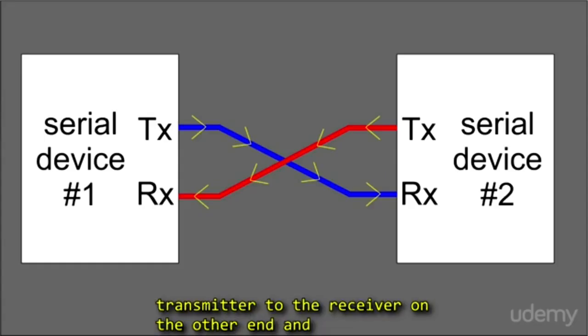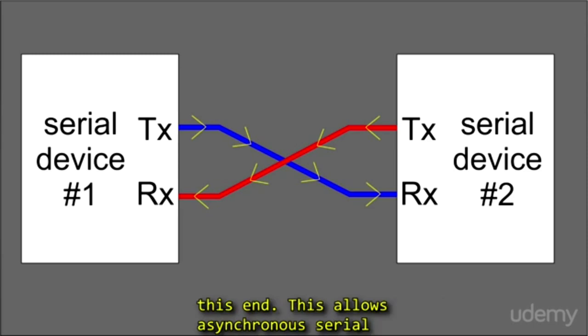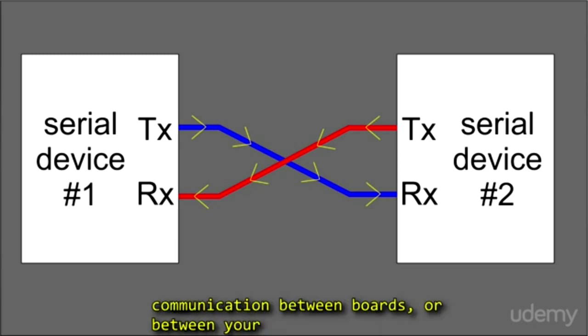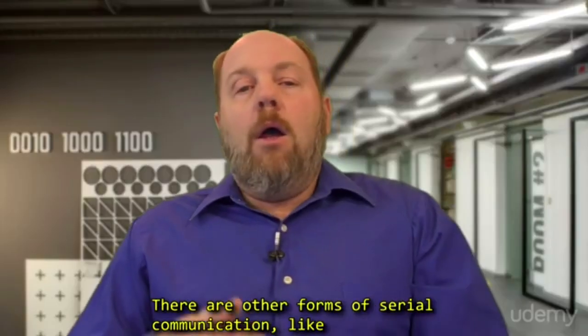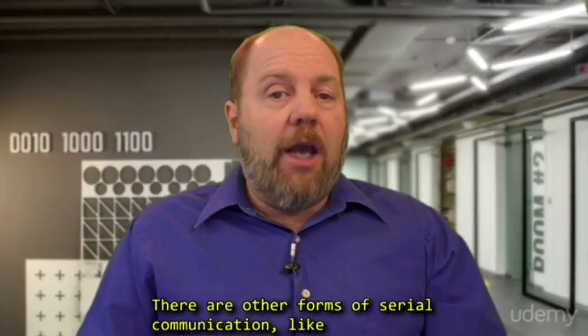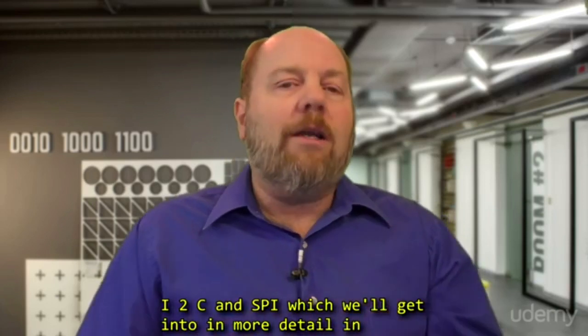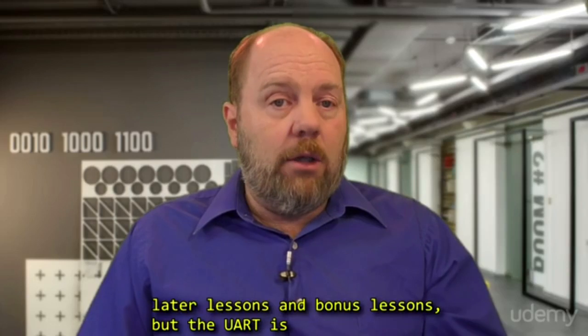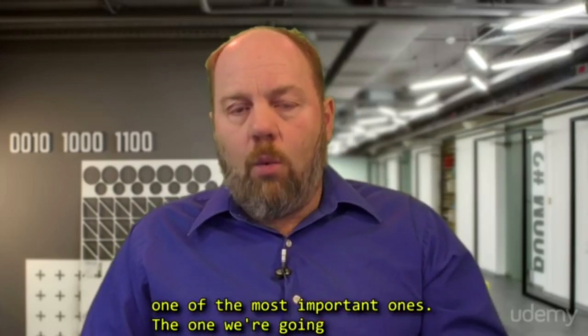You need to connect the transmitter to the receiver on the other end and the transmit on the other end to the receive on this end. This allows asynchronous serial communication between your boards or between your Arduino and another digital device with a UART. There are other forms of serial communication like I2C and SPI, which we'll get into in more detail in later lessons and bonus lessons. But the UART is one of the most important ones.